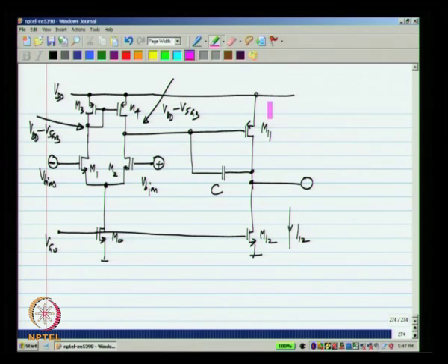Okay. Now, what will be the current that M11 carries if it happens to be in saturation region? To imagine this, since we are discussing DC situation, we can neglect the capacitor. So, let us say I connect the drain of M12 to VDD and M11 to ground. In this case, these transistors will be guaranteed to be in saturation, and I have some current I12 here, which is the intended bias current for the second stage.